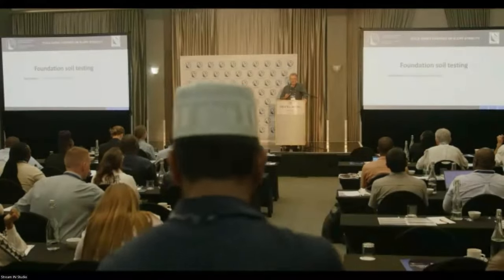One of the things I'm seeing quite a lot of is that often as a TSF gets bigger and bigger, and you perhaps start building a buttress, the critical surface starts transitioning into the foundation soils. So it's not all just tailings related. I think there's sometimes been a lack of focus on making sure we cover the whole spectrum, because it's not just the tailings that's governing.